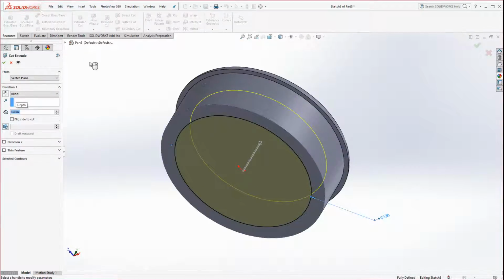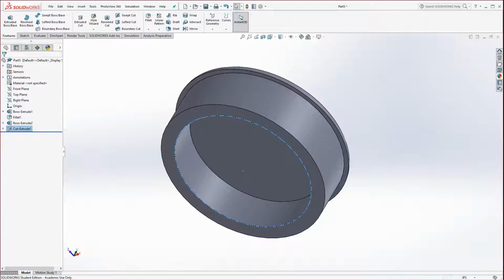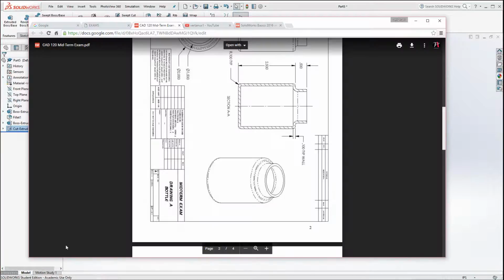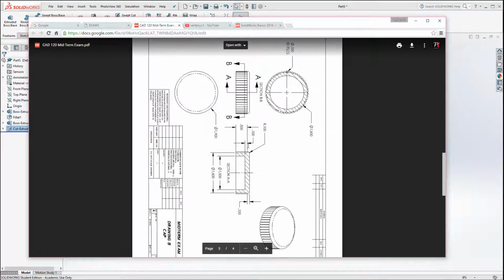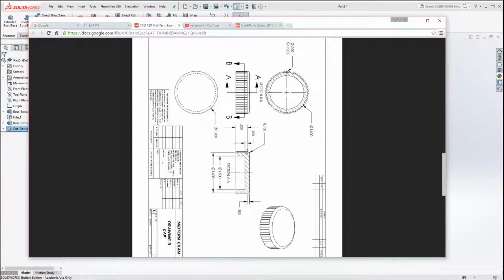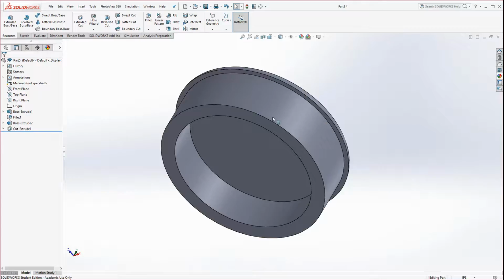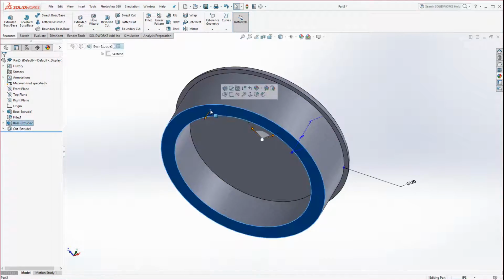And you can see that on the drawing by subtraction. So if you look at the drawing here, and we're looking at the cap, you're looking at this depth right here, 0.5, and then see it goes a little lower, it's 0.1, so it's 0.5 minus 0.1 equals 0.4, so don't make that mistake either, making it the same depth.